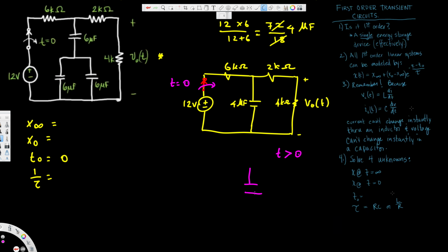So we are going to have this capacitor, and we can find the R Thevenin by simply adding these two resistors right now. 2 kilo ohm, and here we have 4 kilo ohm. Both of them are in series. Therefore, R Thevenin is going to be 2 kilo ohm plus 4 kilo ohm, so the R Thevenin is going to be just 6 kilo ohm. Both of them are in series, so if you add them together, you will get R Thevenin 6 kilo ohm.